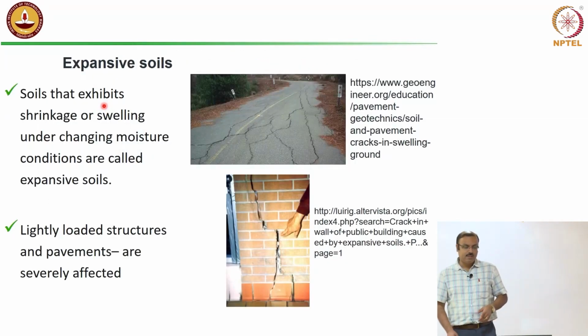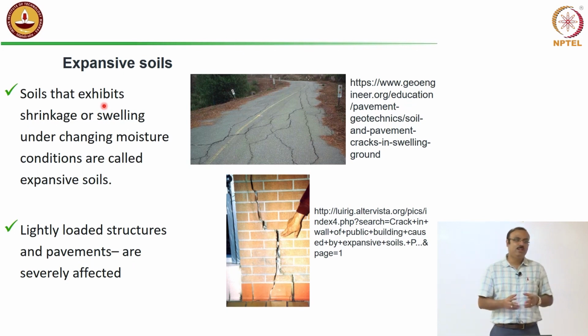Now, finally, there is one more very important thing called expansive soil. There are certain types of soil which have a very bad affinity for water. That means in rainy season when the ground is completely wet, they will absorb the water. Now, while absorbing the water, what will happen? Their volume will increase, isn't it? It's simple common sense, right? If you have a mass of soil, you pour some water, the volume will increase because they will absorb it.